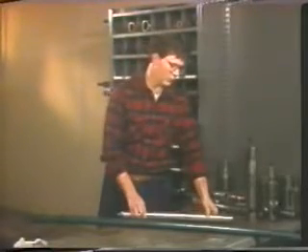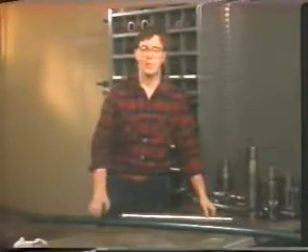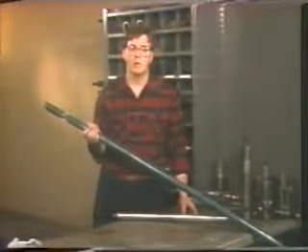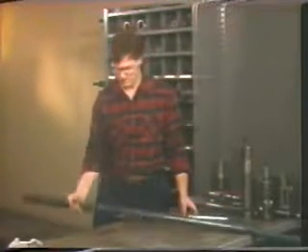Sometimes sand deposits or bridges will build up in the tubing and prohibit wireline operations. If this is the case, some type of baler may need to be run in order to remove these deposits. Pump balers consist of a barrel, plunger, and baler bottom. In operation, the baler is stroked to create a suction which picks the sand up into the baler. To hold the sand inside the baler once it is picked up, the baler bottom is designed with a check valve, which opens on the upstroke to allow the sand to enter the baler, but then closes once the stroke is completed to prevent the sand from falling out the bottom of the baler.